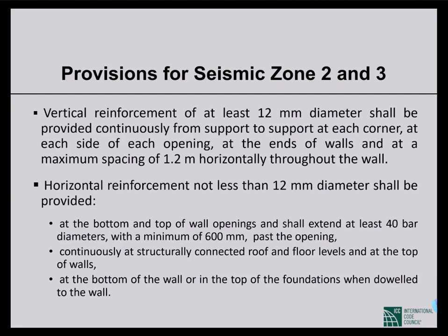So a lot of details. Number one, the bar diameter. For vertical reinforcement, the minimum bar diameter will be 12 millimeters.